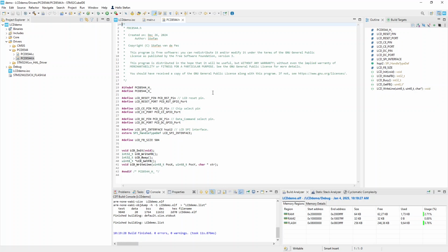These are the pin names we've just annotated. You have to do that also for your specific board and pin selection, but it is very easy. You just assign the correct pin name to the pins that are used by the library software.